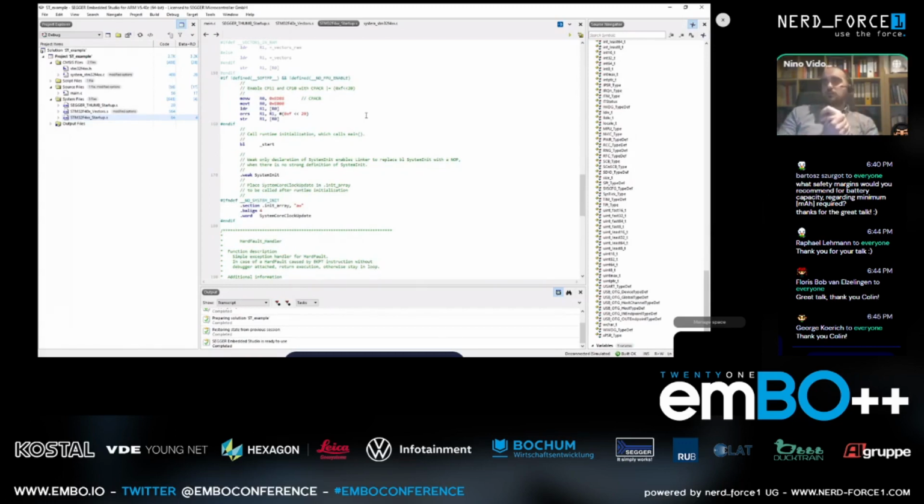But if we would use a soft device here, we would now use the code that comes with your floating point library, which would run completely in software, and whenever you do a multiplication or use a higher level mathematical function where floating points are involved, the library functions would be called.